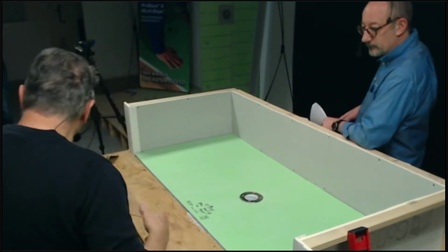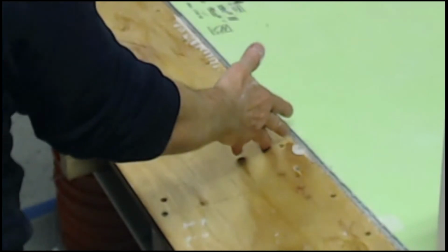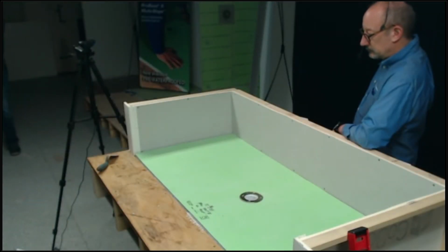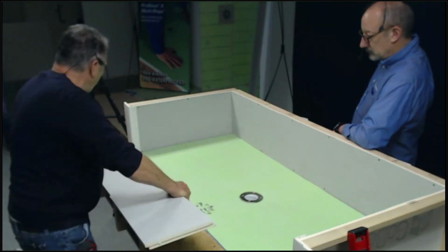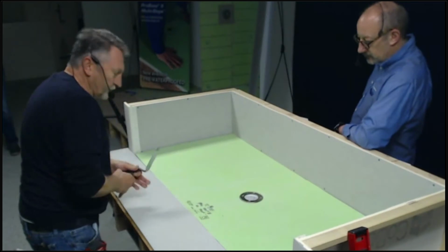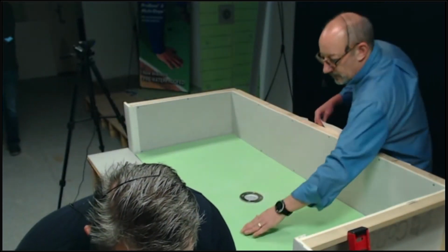So what we're going to do, instead of using the shim, since I only have 1/2 inch at the most, is put a 1/2 inch backer board down. It happens to flush out perfectly. Just butt it up to it, as you can see. I'll put a few screws in it for demonstration purposes, and that's flush out nice.